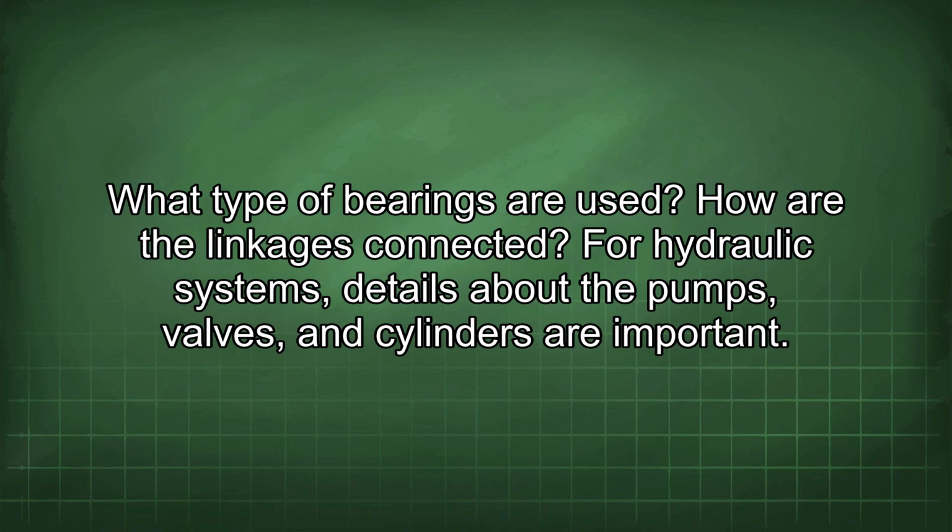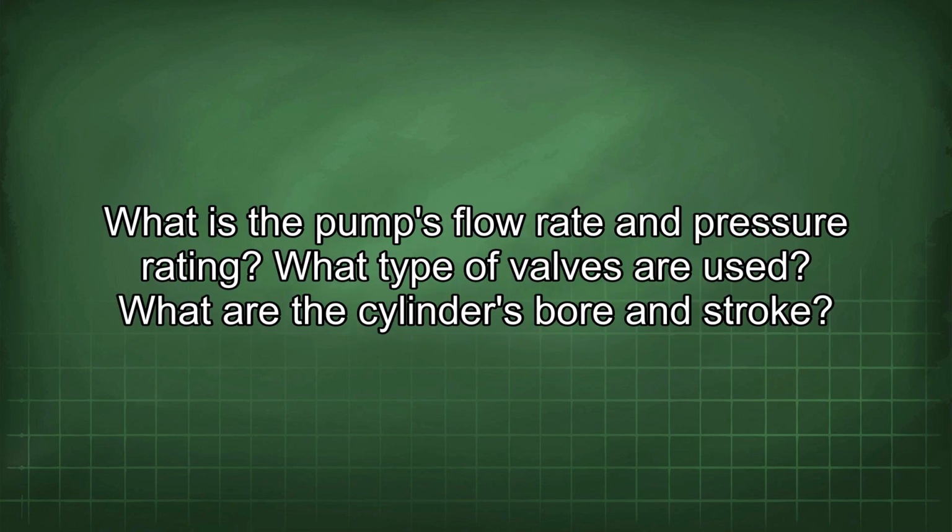For hydraulic systems, details about the pumps, valves, and cylinders are important. What is the pump's flow rate and pressure rating? What type of valves are used? What are the cylinders' bore and stroke?